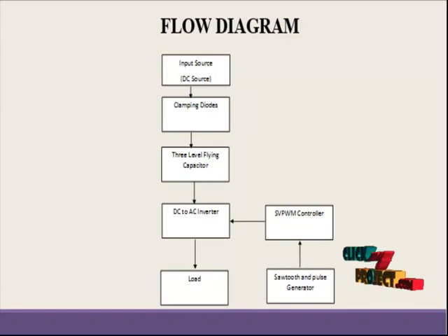In our process, we initially give the input source, which is a DC source. So we give some DC voltage source for the initial input. The structure is made up of three modules. The first module is a conventional full bridge circuit whose switches generate the maximum and minimum voltage for the line to line waveform. The second is the three bidirectional switches in each